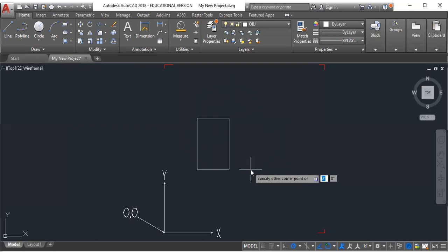So again, we're going to go 40 feet. And you have no reason to know this except that I tell you. The next step is, instead of a hard enter, to go to the next dimension, the height in this case. You type comma, 40 feet, comma, and then 60 feet 9 inches, and enter. And it gives us an identical looking rectangle, this one to that one.